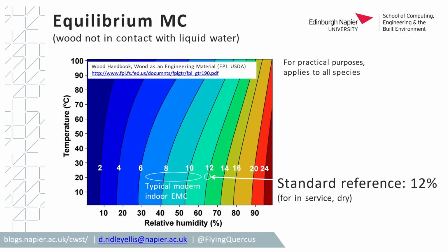We leave them for a period of time. This is a much longer period of time, could be several weeks. We'll have it at a temperature, say 25 degrees and 60 something relative humidity, and we should then get our samples of wood at roughly 12%. We want them nearest 12% as possible, but what we actually want is the aim to come to an equilibrium, i.e.